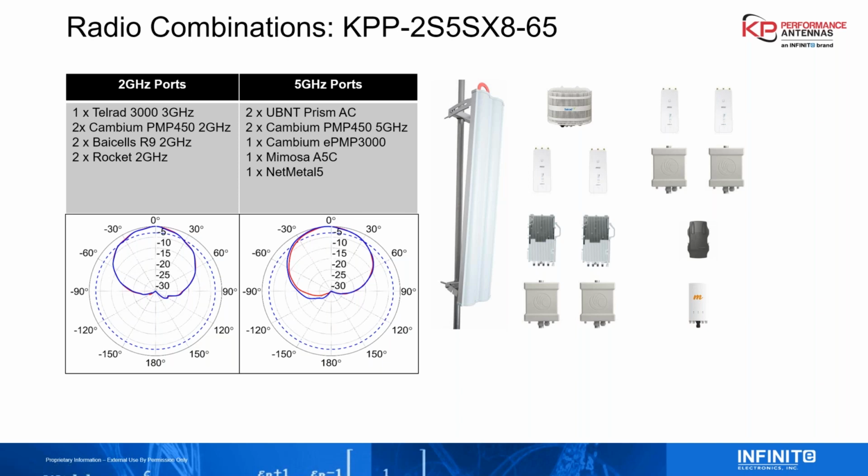The channel spacing is really going to depend on the bleed off from the radios. So how tight are their channels on that radio? The older Rockets, it's not as tight. So I would say as much spacing as you can. I would say probably 10 megahertz if that's possible, as a guard band between the two.